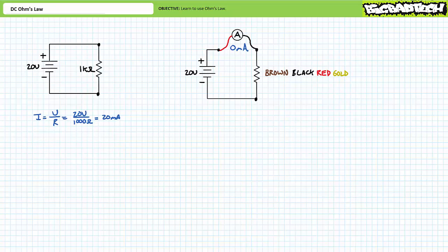First, ask yourself, did you turn the source on? You'd be surprised how many troubleshooting scenarios are resolved simply by pressing the large button that says on. I've done this myself more than I'd like to admit. What if the source was on, and you still observe no voltage drop across the resistor, nor any current through it? Ask yourself, what is stopping current? Perhaps something with an infinite resistance.